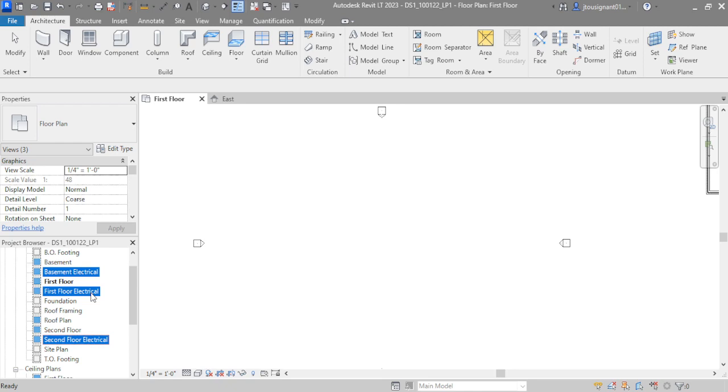But most of the time, actually I will say all the time that I've ever had to express to a client where electrical systems are, I've always had to do it in the ceiling plan, because it just made more sense to have the lights and the electrical systems and then an underlay, which we'll go over, of the floor plan all just kind of be in the ceiling plan system. So I'm also going to delete these electrical plans.